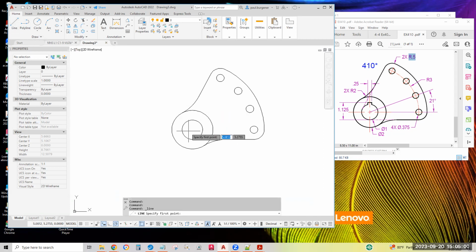So let's draw a guideline from the bottom of the hole straight up 1.125 inches, 1 1/8. 1.125. Enter. 9/8 would work, but you can't combine a decimal and a fraction. I'll hit enter. Bend my cursor. That's the proper height. We're going to cut this 1/4 inch keyway. I'll hit enter or endpoint.